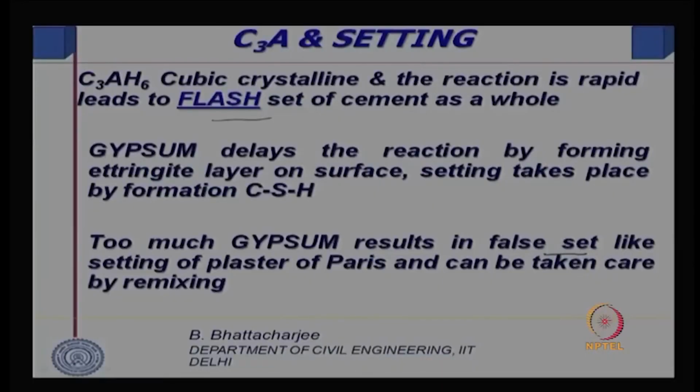Too much gypsum is again not good, because it results in what is known as false set, like plaster of Paris, because gypsum itself will react with water and form hydrated gypsum, like plaster of Paris, and therefore this is also not desirable. This is called false set, but you can remix it a little bit and it will set again.